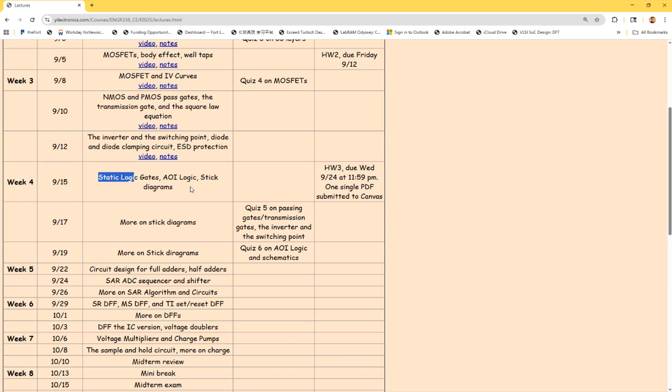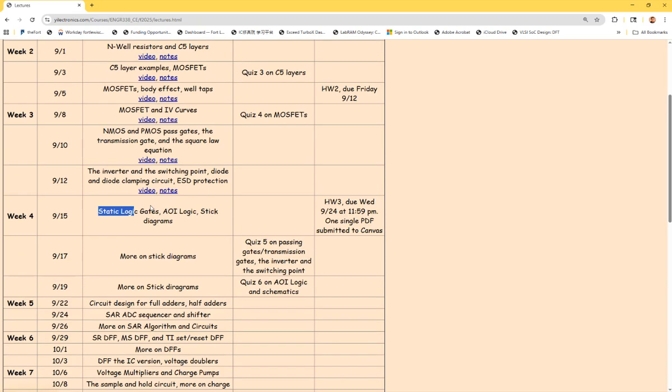But it's still very useful because we are forming gates, we're drawing gates, and putting the gates into a symbol, and we're using the symbol to draw and design larger scale schematics, and we convert that schematic into layouts, and then we compare layouts and schematic. It's called LVS, and if it passes LVS and passes DRC, we claim that as a success of the integrated circuit design. That's how that works.